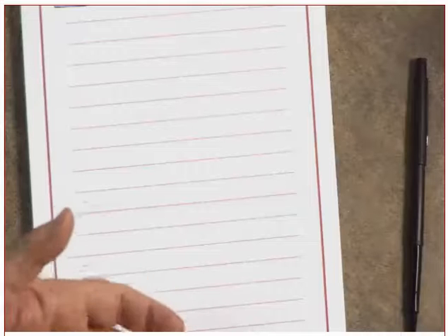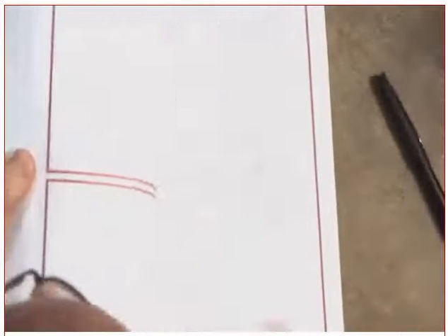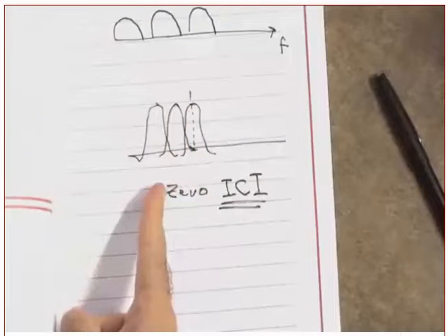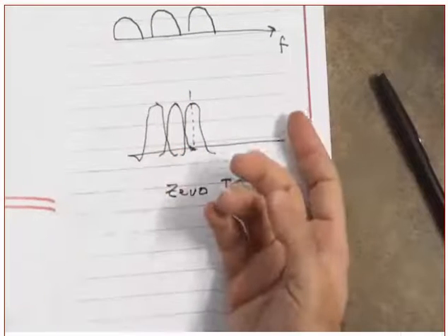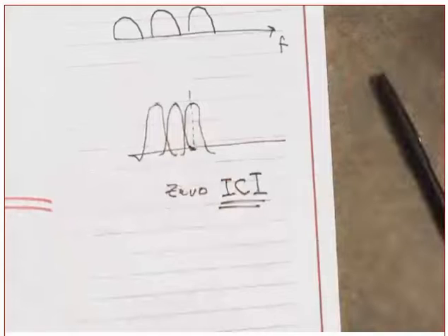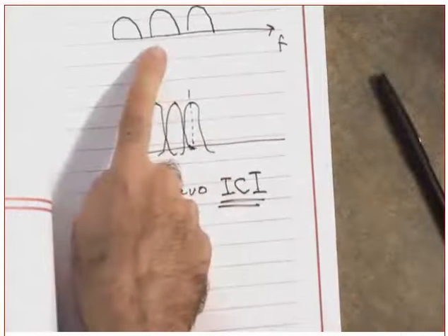Which means one bit goes here, the next bit goes here, the third bit goes here, which means the bit rate has dropped. And you modulate each one of these lower rates on a subcarrier. Those subcarriers are chosen to be orthogonal. Orthogonal does not mean like this. It means like this. Did you get my point or not? Because if it is this, it means we haven't done anything.